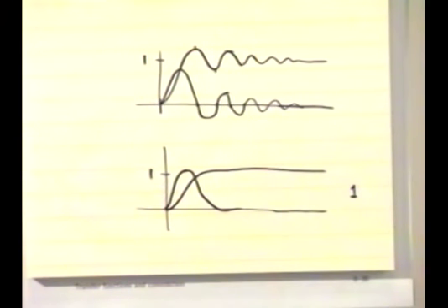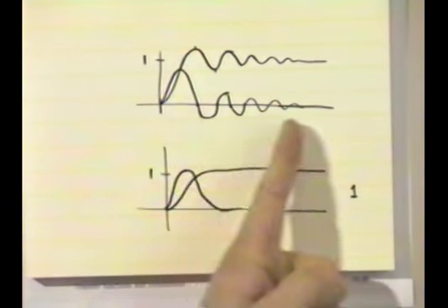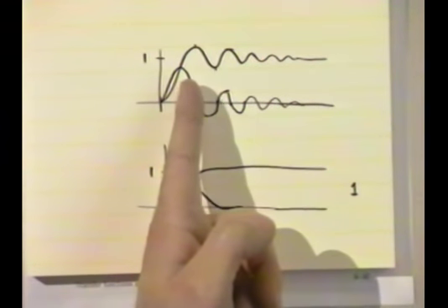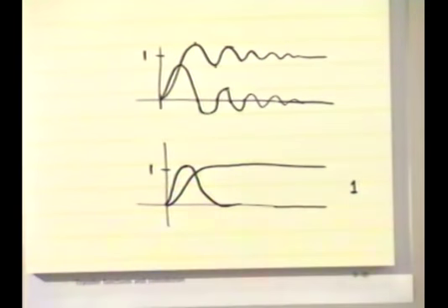Just intuition. What would be a very bad thing to drive over in the suspension system? Just guess. What do you think? A curb? What would it be? Yeah, speed bumps. And how would they be spaced? Yeah, they'd be spaced just like this. If you drove over speed bumps with this thing, and they were spaced just like that, what would happen is, of course, this would be like a swing, and you'd be pumping a swing. You'd go over the speed bumps, each of which is only 10 centimeters high, and out the other end, you'd find yourself with swings up and down that are 40.